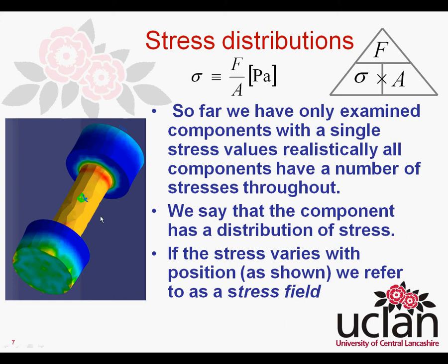The component here, we've plotted the stresses using the CATIA finite element software, and we can see that blue is low stress while we have high stresses in red and yellow regions. So we say that the component has a stress distribution, or a distribution of stress throughout it.